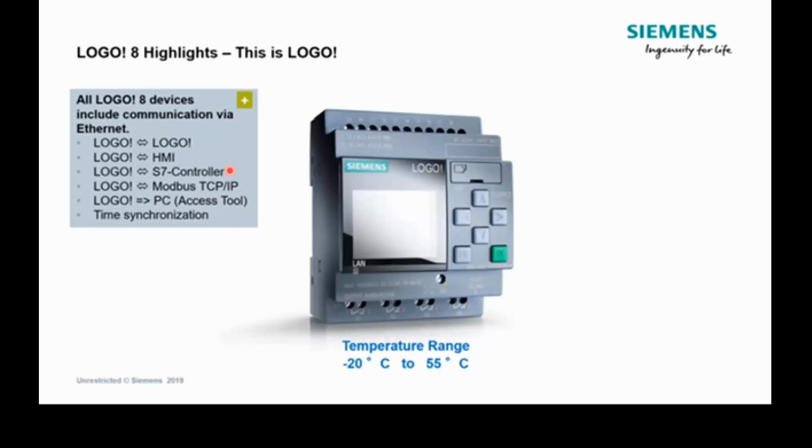As an alternative to that, and a means of gaining access to the outside world via third-party communications, we've also got the Modbus TCP/IP capabilities. So you can initiate client or server comms with Modbus TCP to communicate out to, I don't know, maybe energy meters, or even to utilize Modbus in its true form as its original design as a protocol for initiating remote I/O communications.